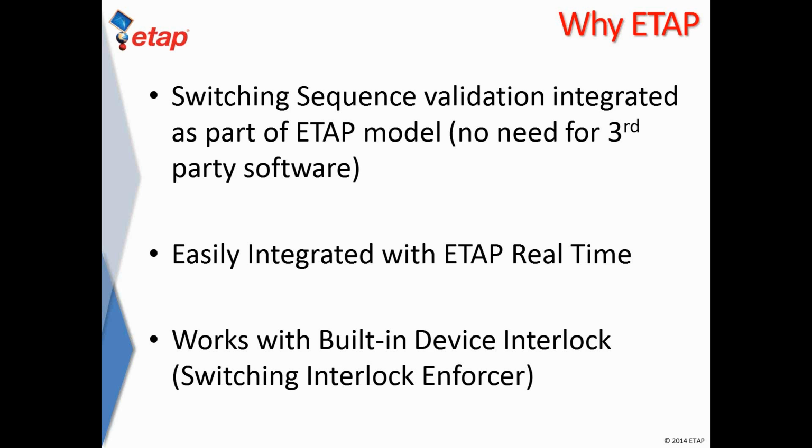You could think of it as a smart HMI, where before the operator actually follows a switching procedure, they would just select it from the ETAP real-time HMI, and based on your existing system conditions, ETAP will give the operator feedback on what would happen if that sequence was executed at this point in time. So you could think of it as a third layer of protection.